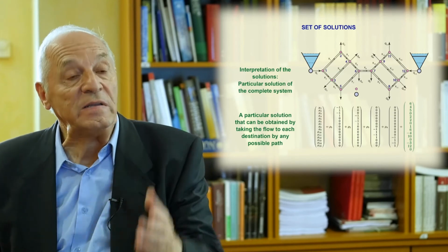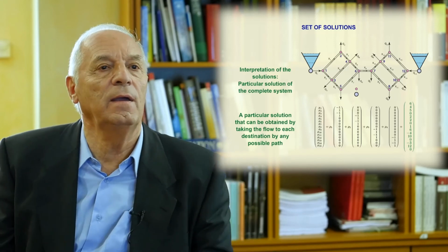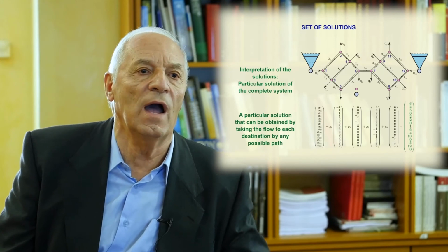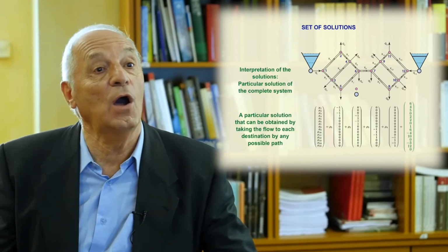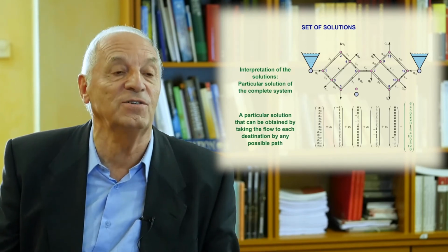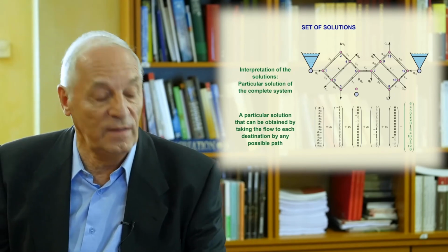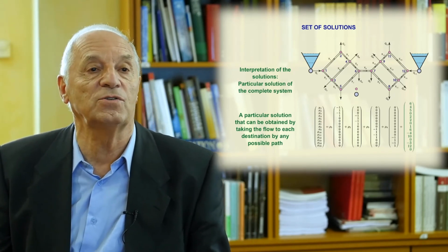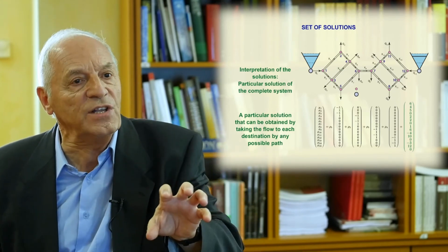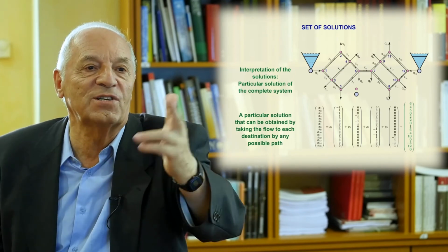So my students are asked to design a different water supply network. Every student has to take a different one. They will have different holes, and they will have different dimensions. They will have different basic vectors, and they will be able to calculate them, and they will calculate also the particular solution. So without using the algorithm, only with mathematical knowledge and engineering knowledge, they are able to write all the equations, and look what a beautiful result.